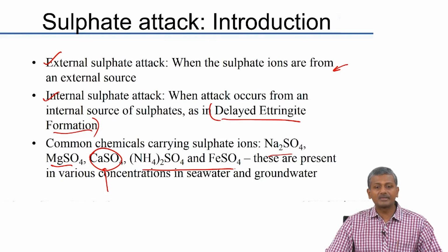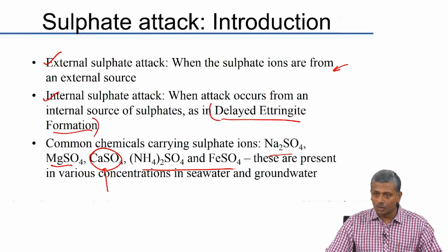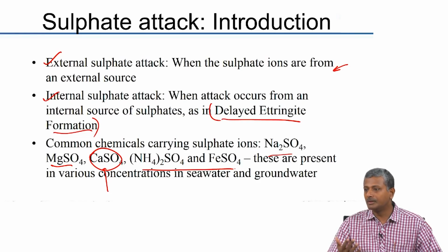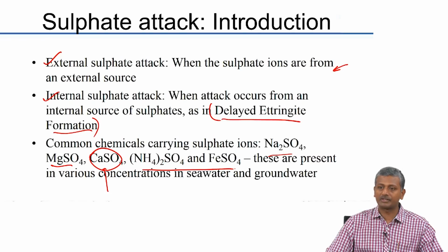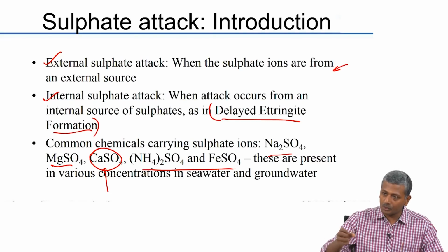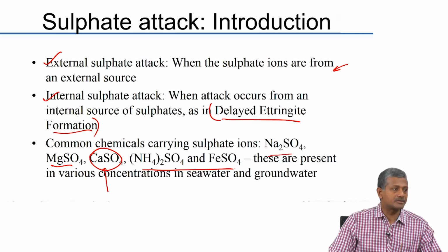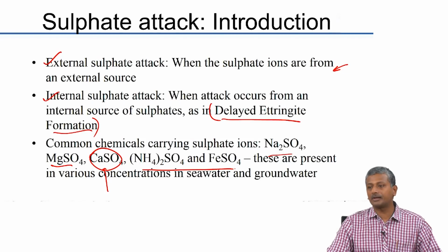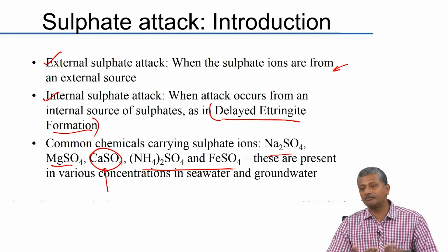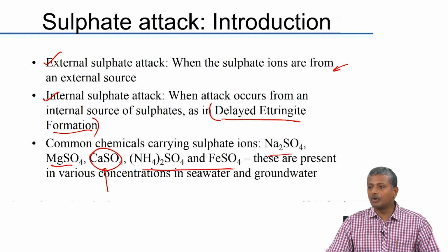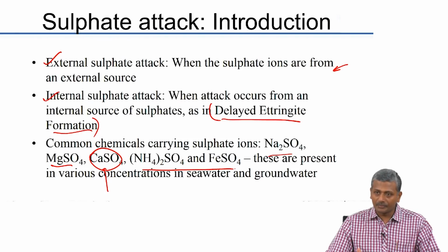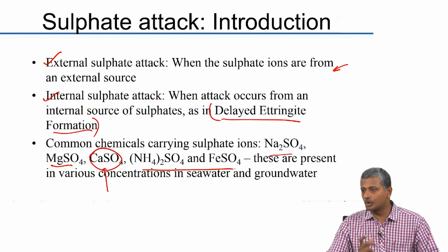Now, why is that important? Why is the solubility important? Only if they are soluble, they can actually penetrate the concrete either by diffusion or by permeation, right. So, getting into the concrete by the sulphate is only possible when you have soluble sulphates present in the soil. So, the groundwater will dissolve these sulphates and bring it to the concrete surface, and then the sulphates will penetrate either based on diffusion or a combined diffusion permeation mechanism, right. So, now what you need to worry about is not just the amount of sulphate in the soil, but how much of this is present in a soluble form.